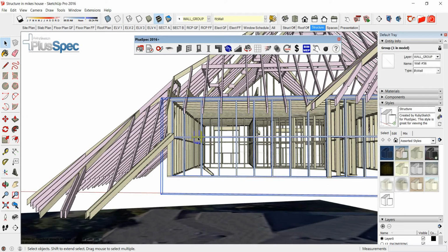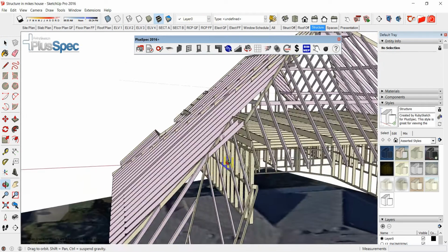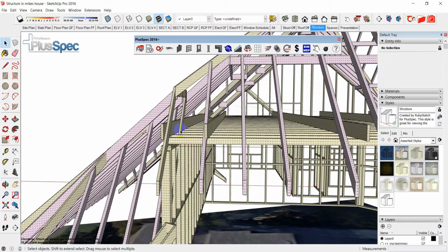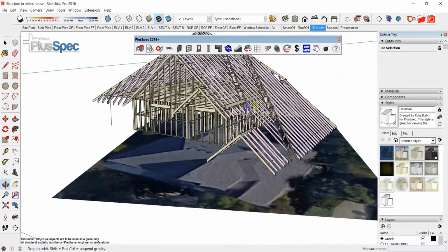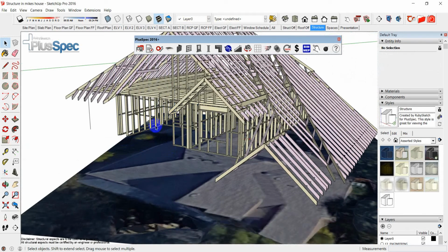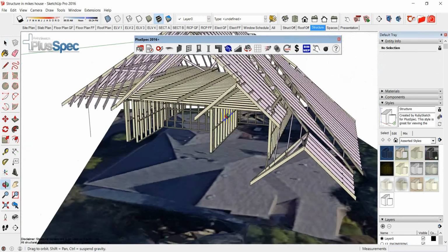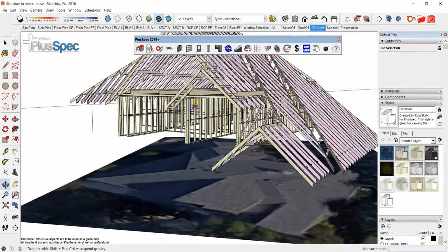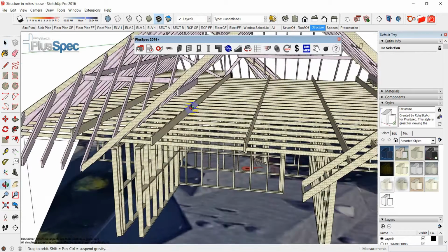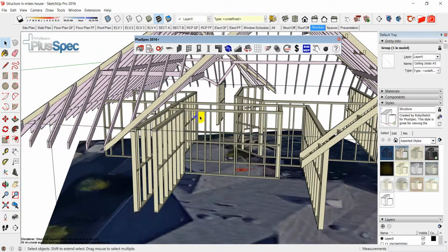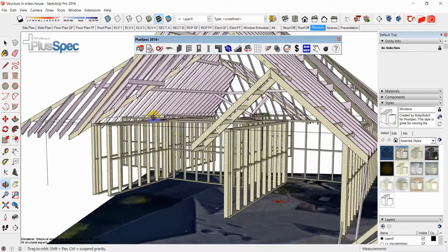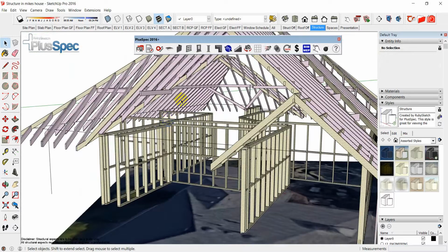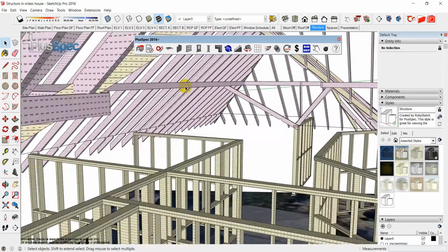So basically the under purlin, this one is actually required. It's still an internal wall, and I'll have a mess around with that in a moment. And over here, these are external walls. I don't need them. So I'm just clicking on them and pushing hide just to hopefully see where I can distribute this load internally. Now my ceiling joists, I don't really need them either, because they're really just sort of getting in the way. And now I can get a lot better idea of where I can start to distribute this load.